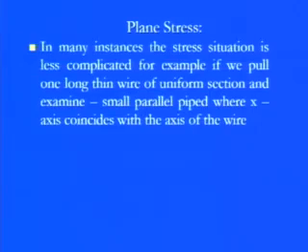So we can simply take a small parallelepiped which is symmetrical, where x is always towards the main direction of load application, and we need only the x as well as the y direction for the total description of the stress. So we do not have to go for the complicacy of those things.